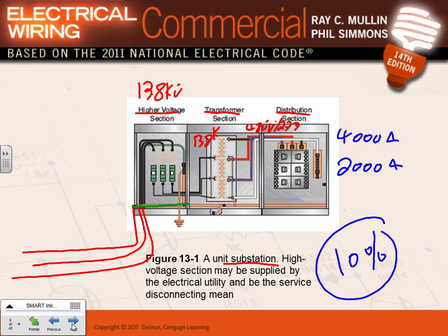I want to bring to your attention, guys, the grounding bar at the bottom here. Can you guys see that grounding bar here? Can you see how they brought the grounding bar here? And here's a conductor coming to the ground and grounding it. That's your grounding electrode conductor.